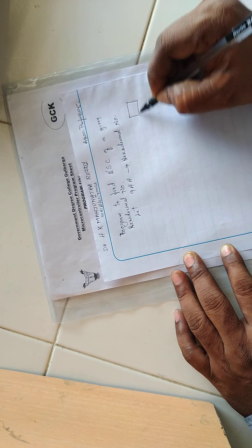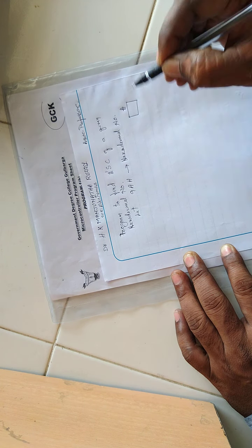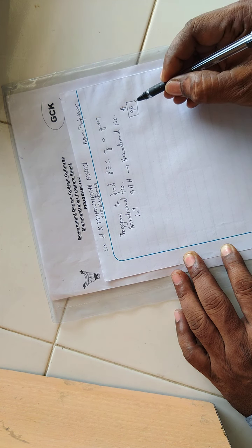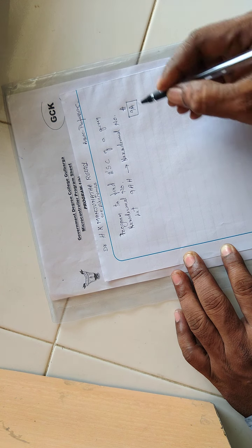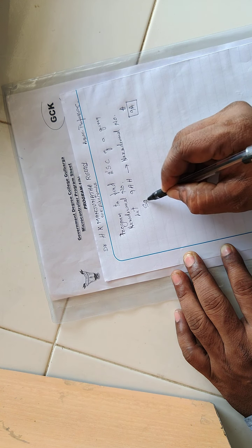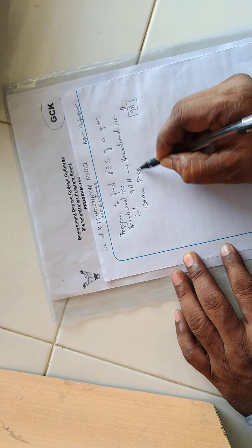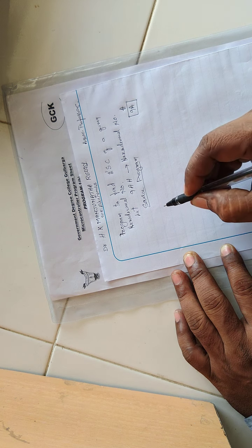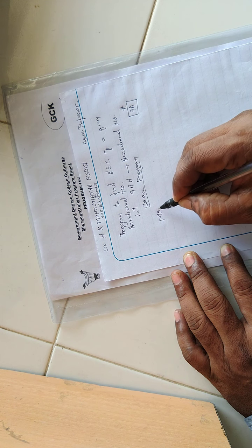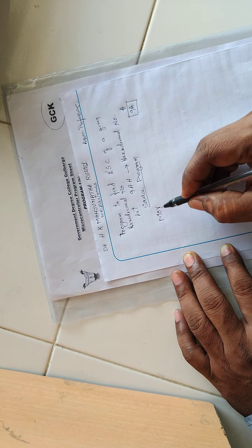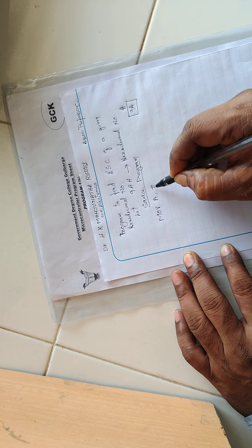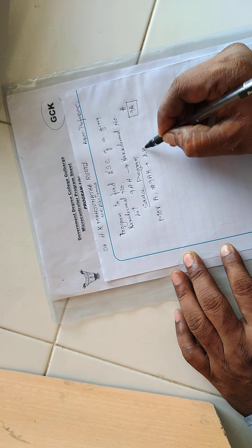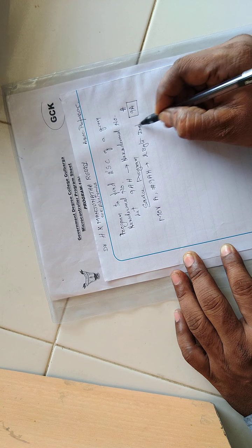First we have to move 9A into the accumulator register, that is an 8-bit register. Then we have to complement this 9A. Source program to find 2's complement of a given number. The instruction used to move 9A into accumulator is MOV A, #9AH, a 2-byte instruction.